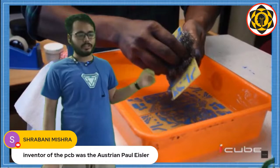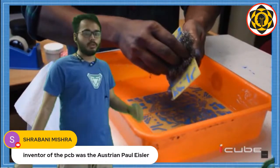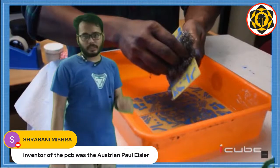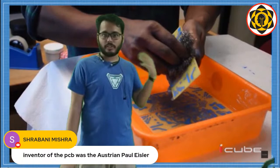Then this is the stage where we are washing it with water, and then we are going to rub it with a steel wool. And why are we going to do that? Because since we have achieved the purpose of keeping these coppers in the places where we want, now we want the copper to be revealed, right? Otherwise we cannot work with it.